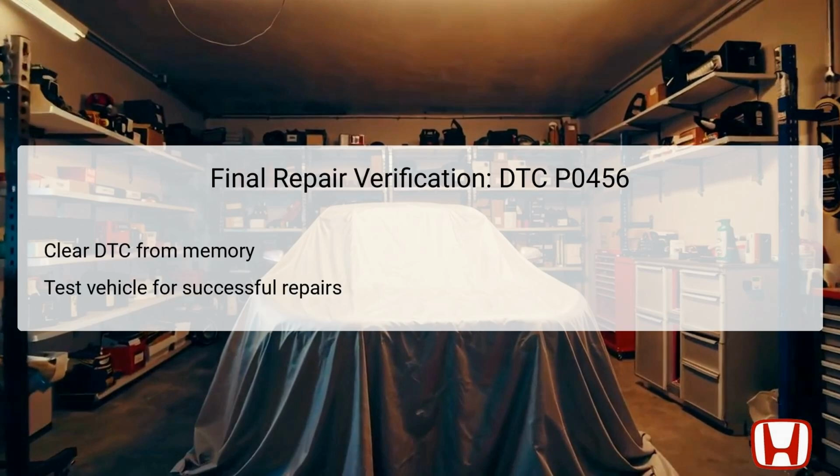After repairs have been completed, the final verification step involves clearing the DTC from the vehicle's memory and monitoring the system's performance during a test drive. This process should involve driving the vehicle under conditions similar to those experienced prior to the repair, ensuring that the original issue does not reoccur.